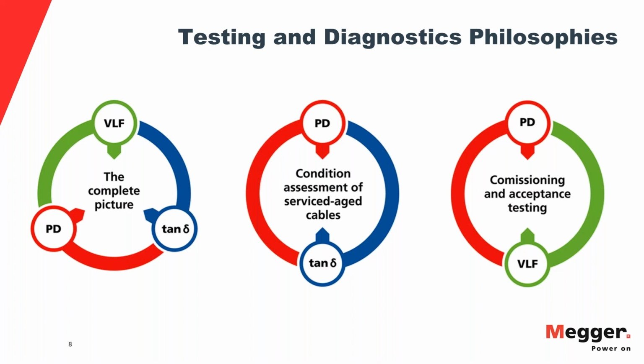And as you can see, PD testing is also in the other 2 circles when it comes to being a tool for the condition assessment of aged cables and also being a tool for getting results during the acceptance testing of new installations. So keep this whole thing in mind. That's pretty much where PD, this is the general kind of application for PD testing.